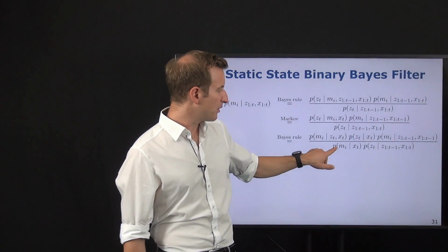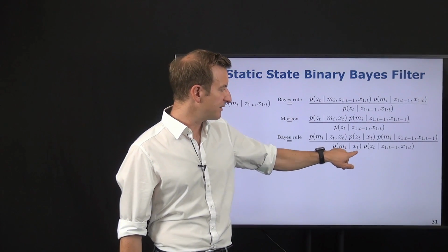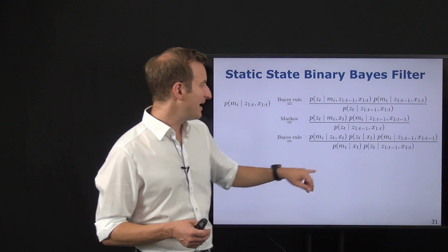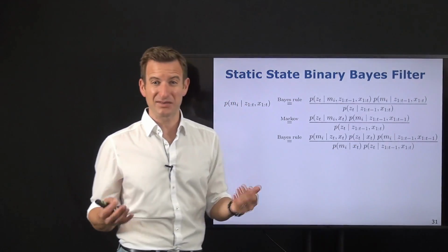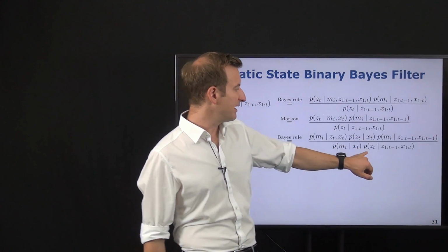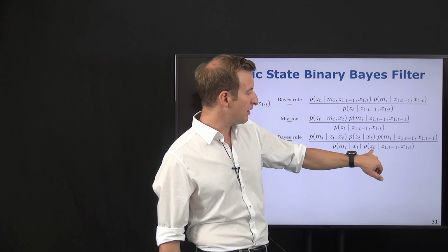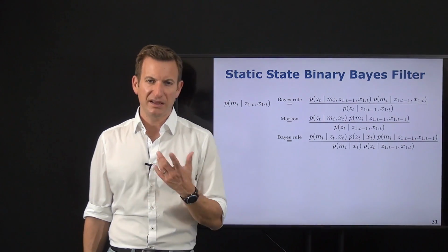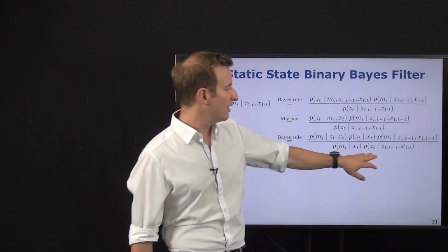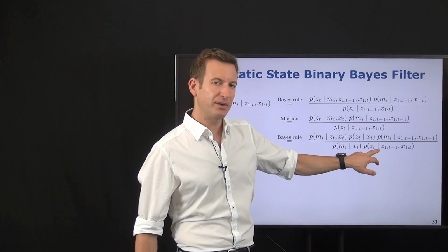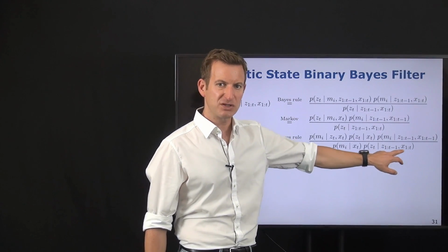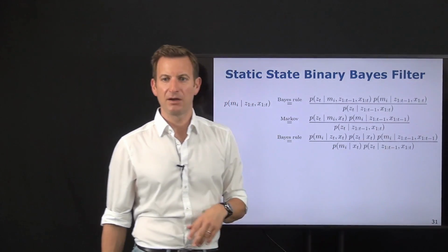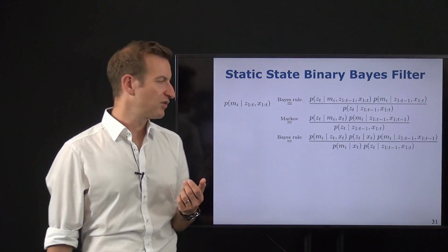And then we have down here the probability of a cell being occupied, given I know where I am, without any sensor information. Also probably something which may be tricky to estimate, or maybe the position information doesn't really help me, at least in general. And then I have P of zt, the probability of an observation given the past observations and the past position information. Again, that's probably tricky to estimate because we don't have a map and we have no idea where we are. We have a sequence of observations taken at different points in time. I can start estimating a map from that, but then I have no idea where this observation has been taken. So this is a term which is probably hard to estimate.